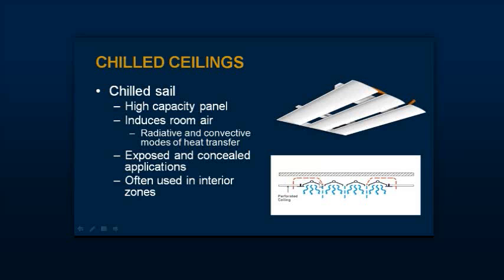Now the building did achieve LEED Silver. It potentially could have gotten more. I'm not certain what the math was, but with 67% energy reduction compared to overhead mixing, that's phenomenal. It's really too bad we can't do that everywhere. I live in Atlanta. My humidity levels alone would say, hey, no, wait, sorry. Because what they did was they used ground source heat pumps as part of the system to provide the cooling media, heating for the water, and then 100% outside air. If you have a conducive environment like where this building is located, you can do that.